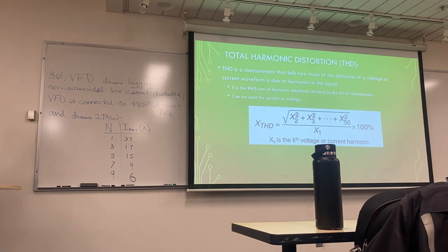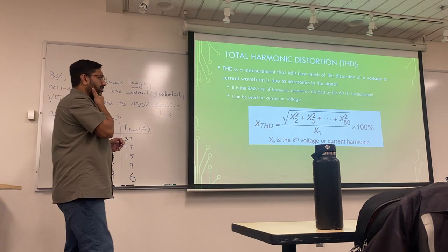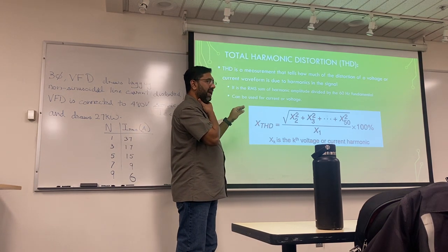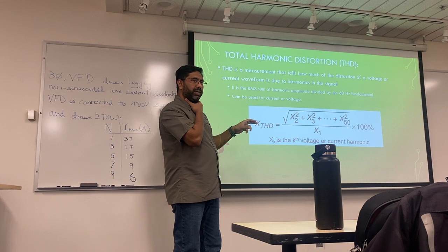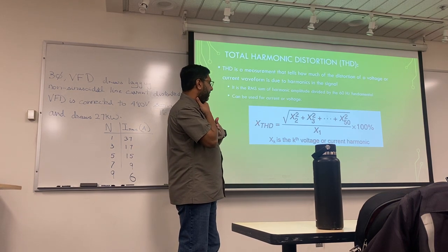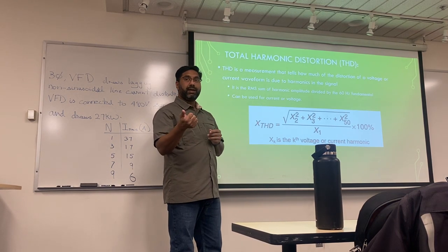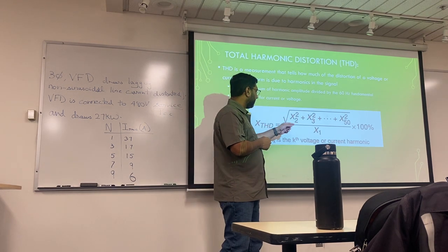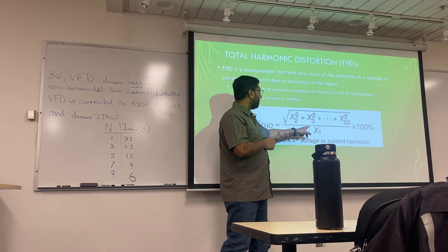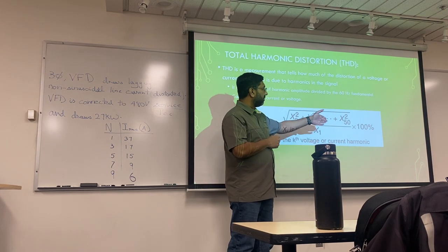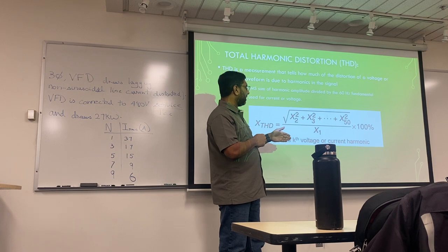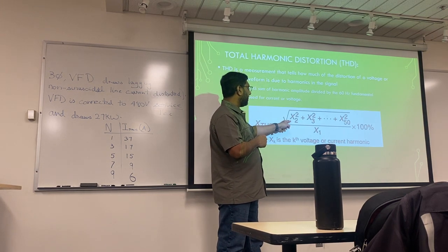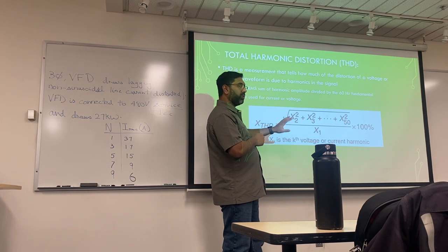So how do you calculate harmonic distortion? It's calculated in percentage. At every frequency there would be a certain current that you get, and I'll complete the derivation that we started last week, and that should tell you what these currents are. So for the time being, assume you have a bunch of currents coming in. So it's not just your fundamental. Your X1 is your fundamental. X2 is at 120 hertz. Current or voltage, it could be either.